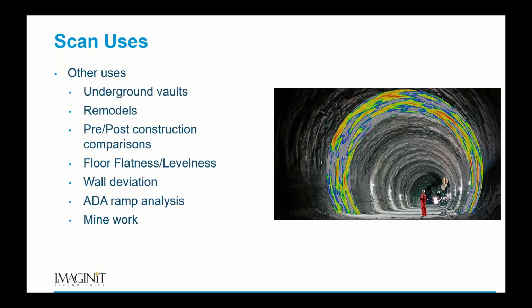Another one is pit mining, scanning the inside of a pit, whether it's downtown Chicago or New York, where they're building a high rise. They've got everything shored up, scan it each week, do a deviation analysis to make sure those walls aren't leaning in, making sure we're monitoring, making sure that we're doing safety. Same thing with mine work comes into play.